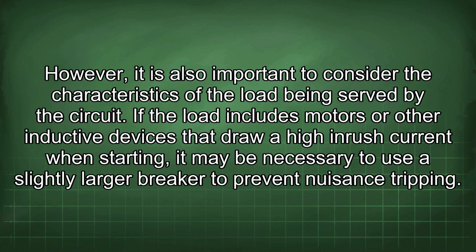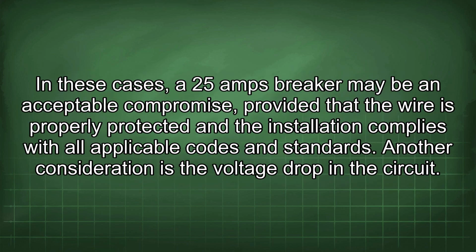circuit. If the load includes motors or other inductive devices that draw a high inrush current when starting, it may be necessary to use a slightly larger breaker to prevent nuisance tripping. In these cases, a 25 amps breaker may be an acceptable compromise, provided that the wire is properly protected and the installation complies with all applicable codes and standards.